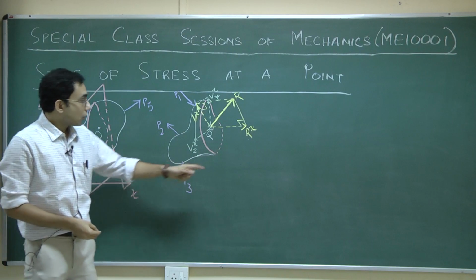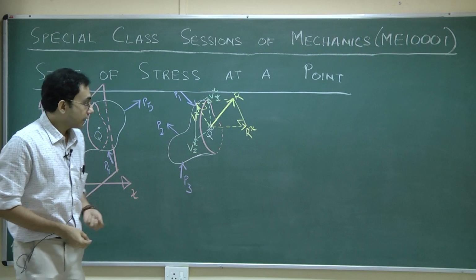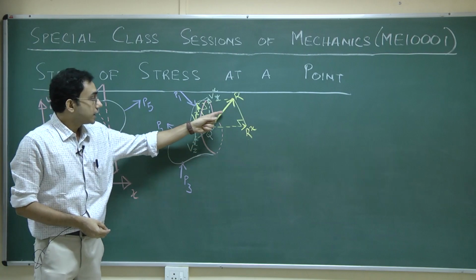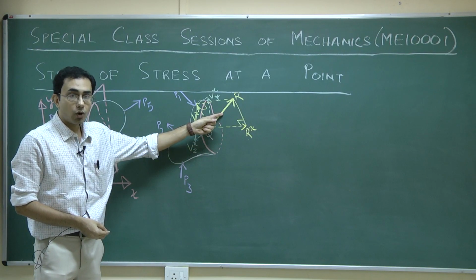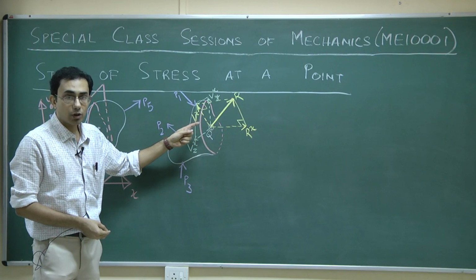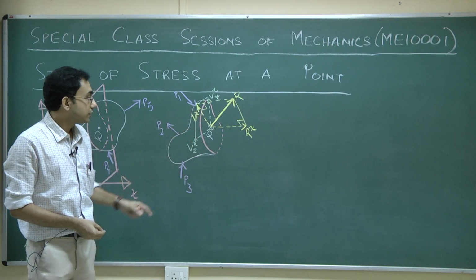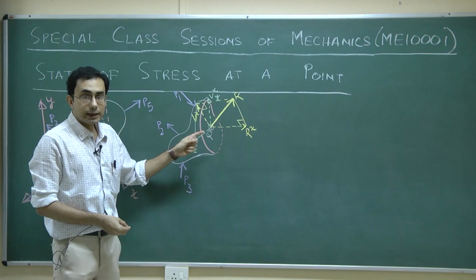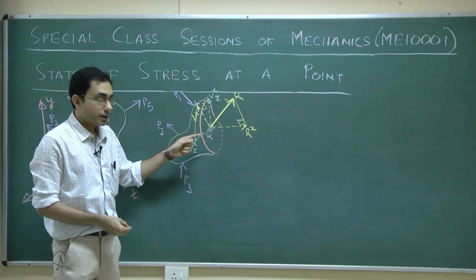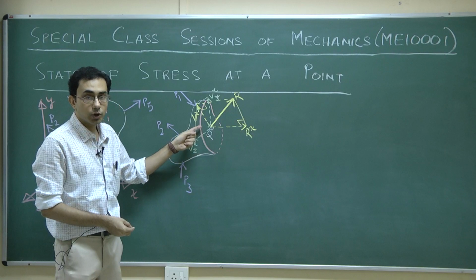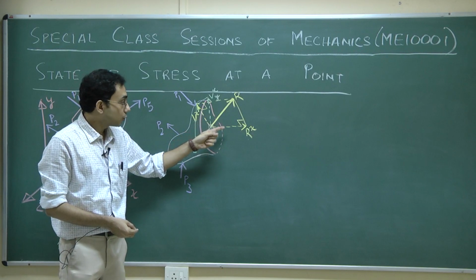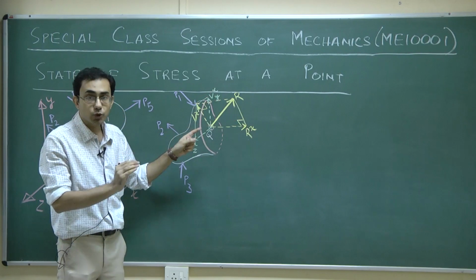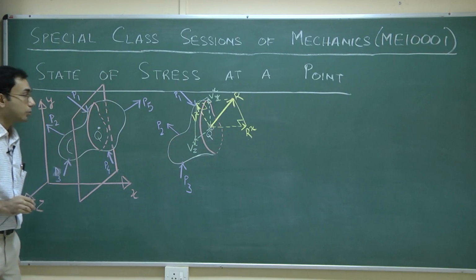The significance of the superscript x here, as you may have already figured out, is that it represents force components of an internal force R on such a plane on which the outward normal is parallel to the x direction. I repeat, the superscript x represents the outward normal direction of the plane that we are considering here. It has nothing to do with the direction along which the force components have been taken.